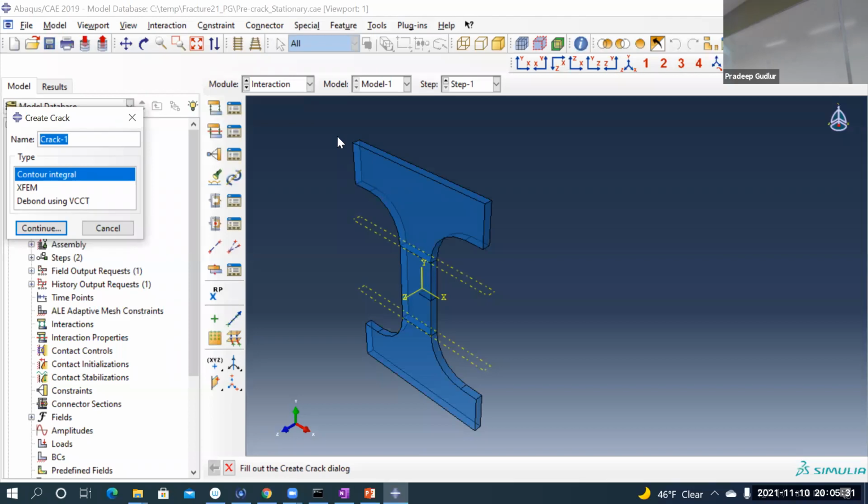They're really good for pre-existing cracks. Already you know the crack direction, where it exists, where it forms. For example, this particular exercise, you can use those. And it depends heavily on mesh. Only if there is an element going in that direction, along that element edge, will a crack form using this method.